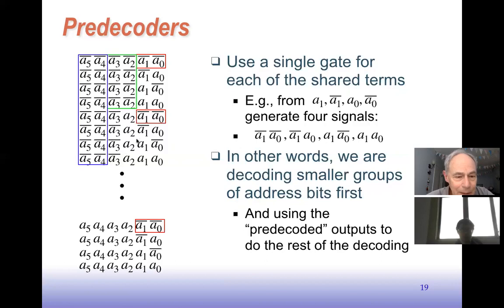And then this pattern here will appear twice. And then on the low 2 bits, we'll have these repeating patterns that keep showing up. So there's a fair amount of redundancy in this decoder function, so it would make sense to try to make it cheaper. It would make sense to factor out those common terms and compute them only once and then share them wherever they're needed.